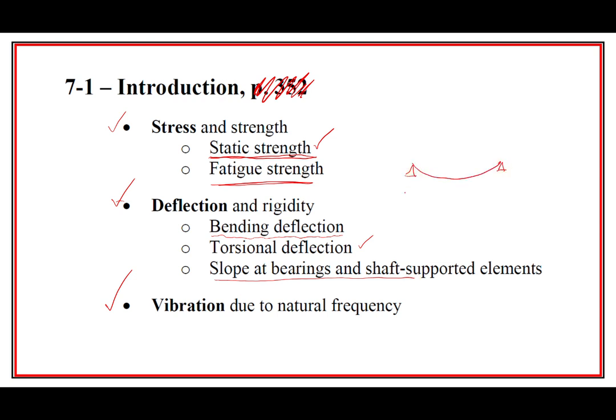We're treating these things like simply supported beams, but the bearings really aren't a good simply supported model. They're close enough, but there's a limit to how much deflection slope you can have right here, and how much the bearing will allow for that type of sloping, or angular deflection, let's say.